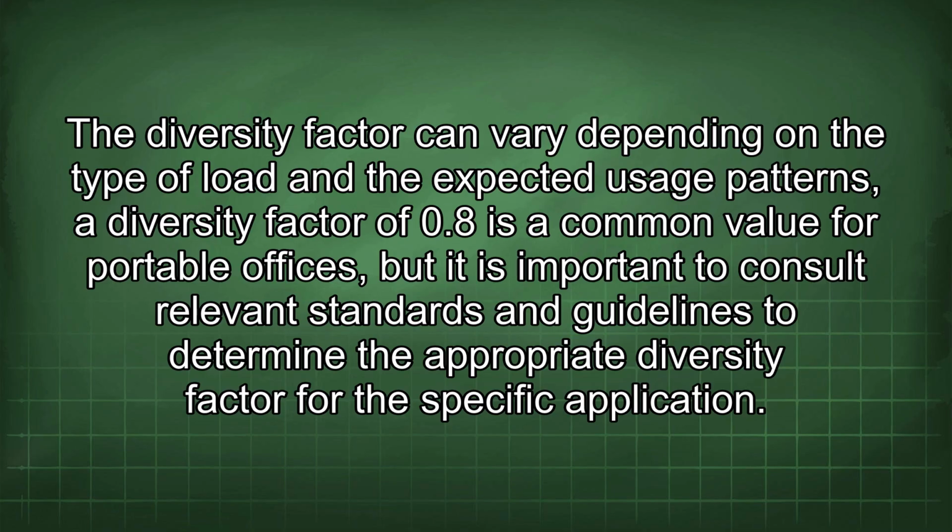The diversity factor can vary depending on the type of load and the expected usage patterns. A diversity factor of 0.8 is a common value for portable offices, but it is important to consult relevant standards and guidelines to determine the appropriate diversity factor for the specific application.